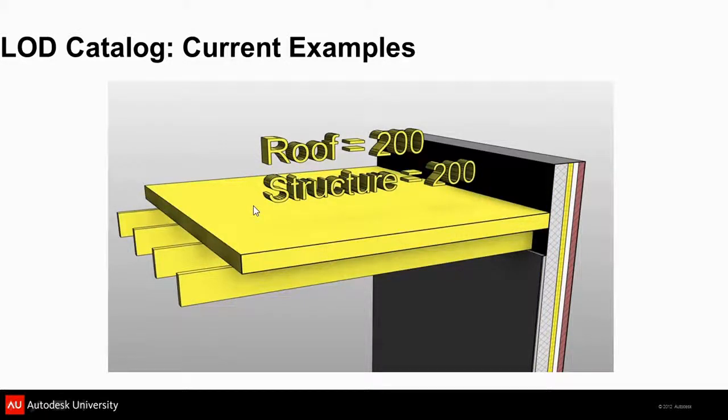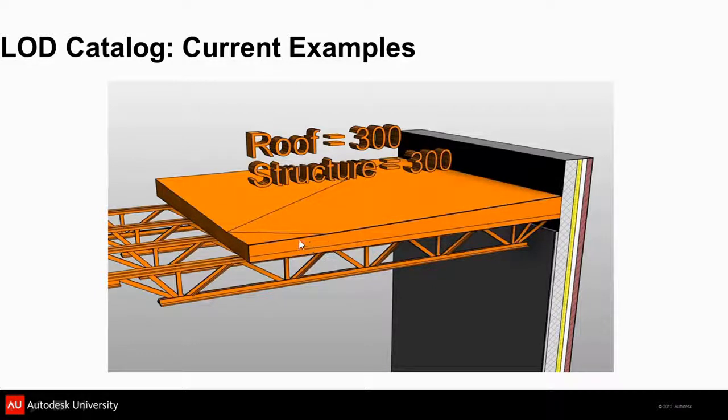As it progresses along, in a traditional delivery design development, you might find elements nominally at 200. And then as you progress to where the elements are at 300, these are the bar joists. As you might have heard us mention in the last presentation, if you were in it, these bar joists are a manufactured product. You can't run your plumbing within that bar joist space until you know the exact web profile from the manufacturer. So you could get a designer's model, but it's really eye candy if you want to run your systems up in the level of the bar joist.